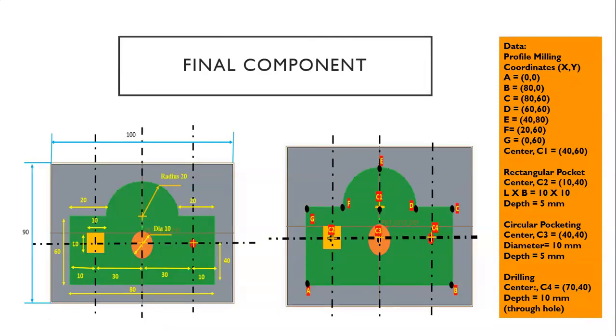So first, what should we do is study the drawing you have been given. First you need to fix the datum. Generally in milling we consider the bottom left as the datum, not the profile. We did not bring the raw material, so I take the bottom of the profile as the datum, nothing but 0, 0. From here you need to identify the other coordinate values.